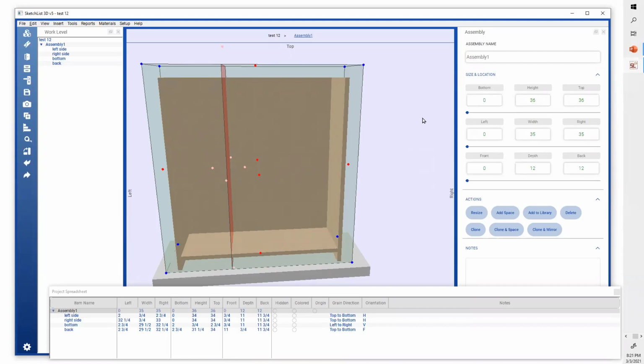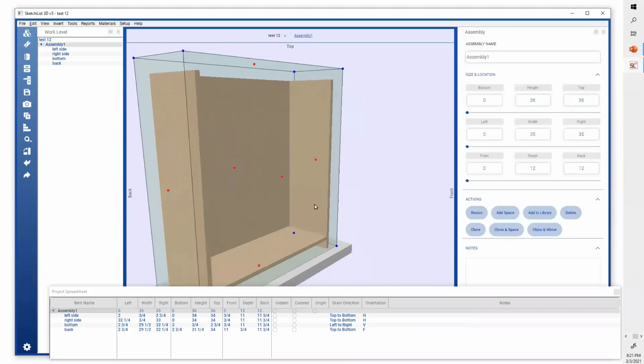And the rule is anything that pink box touches is going to be increased in size to the right by the increase amount. At that point, I think it was 13 degrees or inches, whatever. Anything that pink plane touches gets cut. And you can shrink too, so it would shrink there. Anything that is to the right of the plane and not touching it gets moved by that amount. And anything that's to the left and doesn't touch the plane just stays. So that's how we do that.